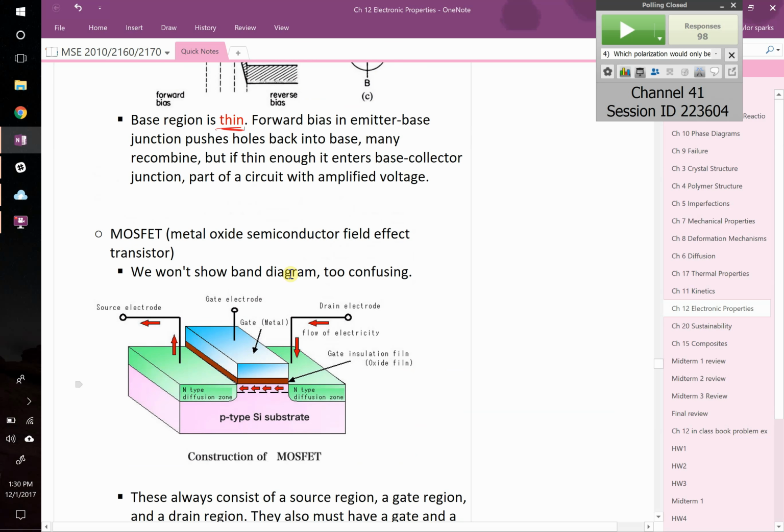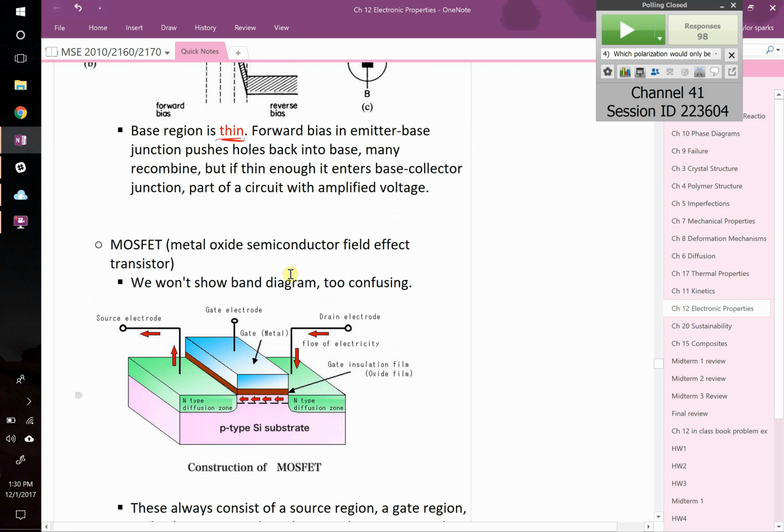Check this out. You've got your basic substrate. This is silicon. Let's say you grew the crystal and it's p-type, so you added some number of acceptors. So it's mostly p-type. But then, using any means you want, masking, ion implantation, there's lots of tools, you bombard certain regions of it with tons of electrons, or donors. So this is mostly, say, arsenic doped, and these regions might be boron doped. Other way around, this is boron doped and these would be arsenic doped. Then you've got N-type and you've got P-type, so you've got a PN junction built in, which means if you turn it on, you're just going to make an LED. That's not useful.